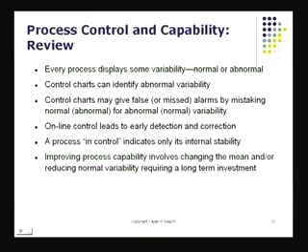If you're worried about is there some way I could get an idea of how good my process is, how poor my process is, look at your control chart. If there are a lot of statistical points, these are the X bar values or the R values, beyond the control limits, clearly it's not very likely that your process is capable. This is something you've got to worry about.